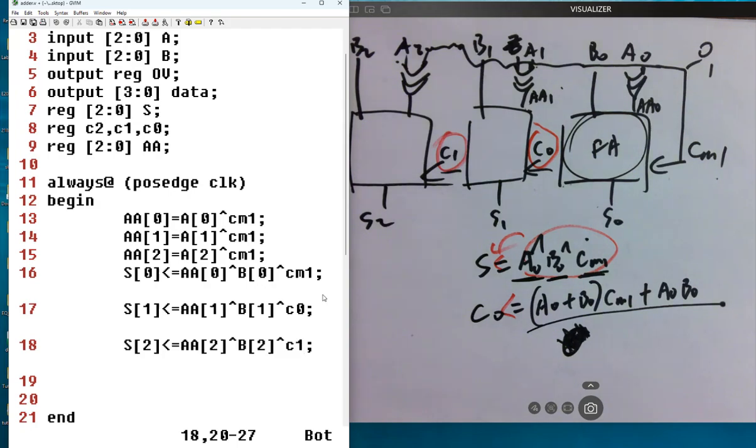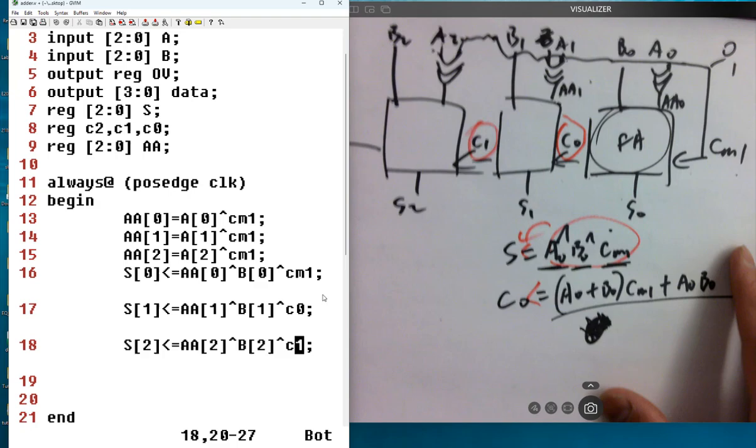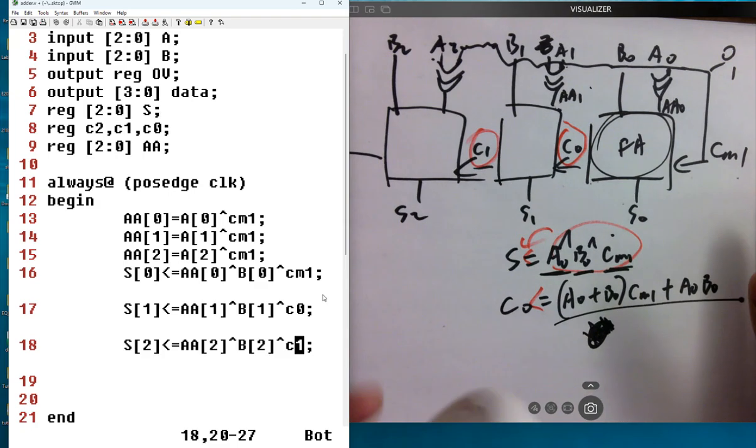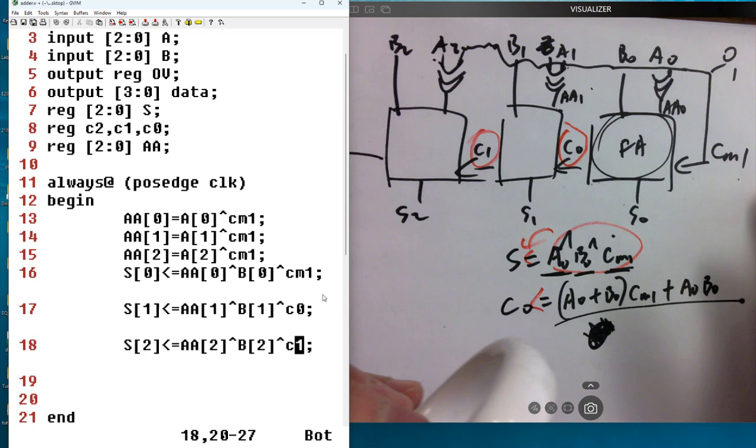So that's why you want to always draw the diagram, draw all the intermediate signal nets or ports physically, so when you're coding it up, you can look at it, right? This is basically a hardware description. So on a resume, you don't want to put Verilog as a software skill. It's not software. It's hardware modeling. It's coding, but it's not software.